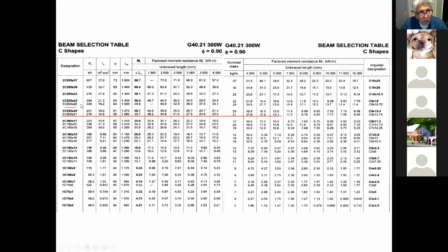Now, what happens here is that you got to make a decision, okay? It all depends on the architect. It all depends on, you know, there's a number of factors. Let's say you make your exterior column. This is a plan view of your exterior columns, okay? These are your exterior columns, both your wind columns and everything else, okay? And so on. Now, if you design your exterior columns W200 by something, okay, then you know that the nominal depth of your column is about 200.